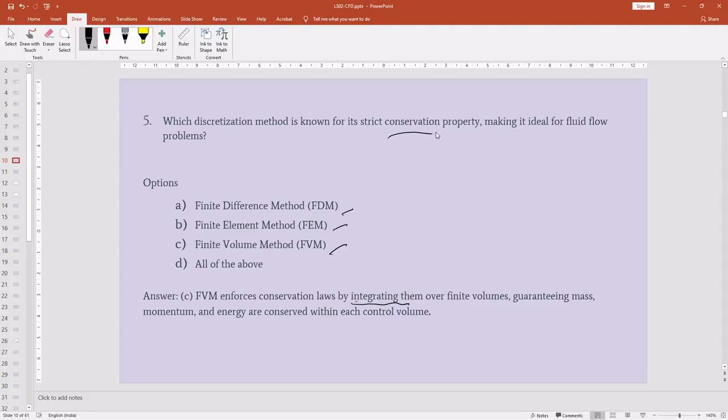So what we will be doing is applying this conservation property to one particular cell. We will be finding the discretization equation, or the governing equation, for a cell, and we will be integrating over the volume. As a characteristic of the method, finite volume is inherently conservative.